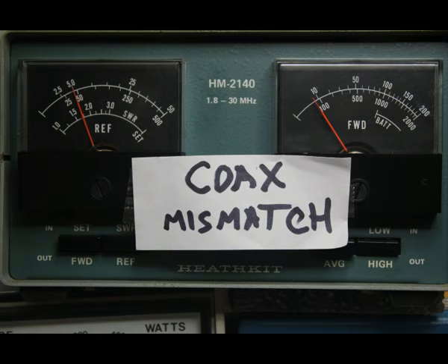And we see that the reflected power says that it's just below 50 watts. So if we subtract, let's just say this is 90 watts, if we subtract the 40 watts or so, maybe that's 50 watts, 40 watts, I don't know, it's hard to tell down at this end of the scale. Let's call it 40 watts. If I subtract the 40 watts from the 90 watts of forward power, we're going to wind up with about 50 watts of real power in the coax.